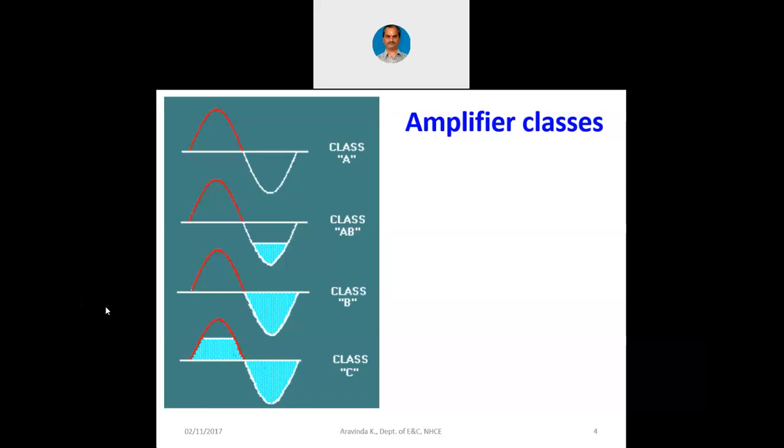As the carrier's wave shape is not important for us, only the information signal's shape is important for us. Now, the radio amplifier is going to carry the voice information. The voice information is amplified by an audio amplifier. The audio amplifier has to be class A. The radio amplifier can be class C. That is how we save power in the case of a class C amplifier.